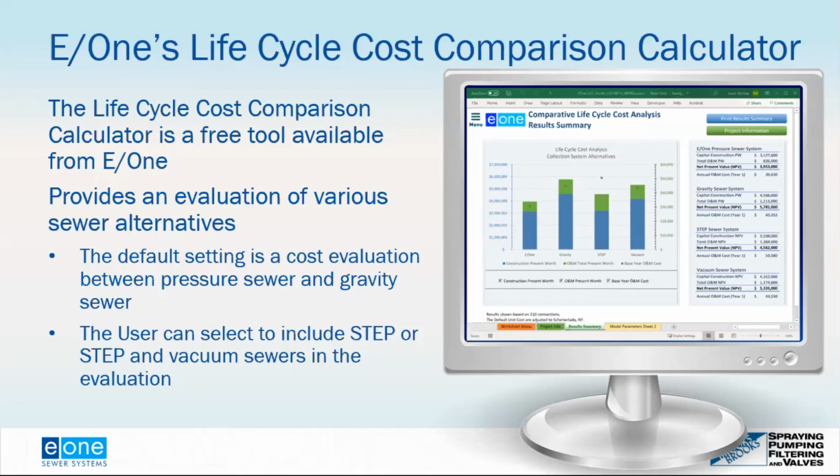Yeah. And like I said, what some of our developers do is they'll go through and zero out the numbers, so it doesn't even show a total O&M cost. I found it quite enlightening that, like you said, the low pressure sewer is usually in that 35% less cost overall when you look at the analysis compared to gravity.